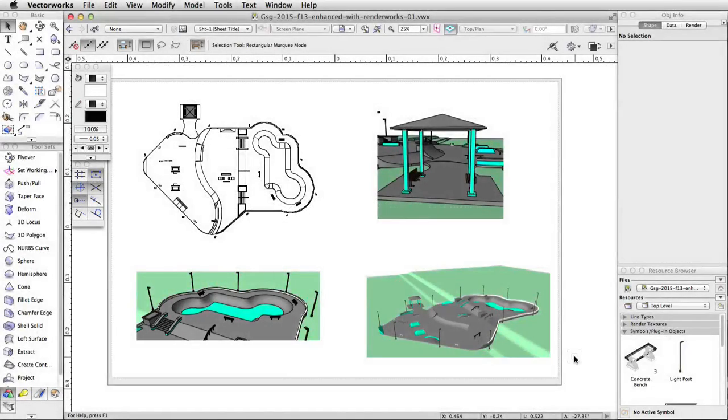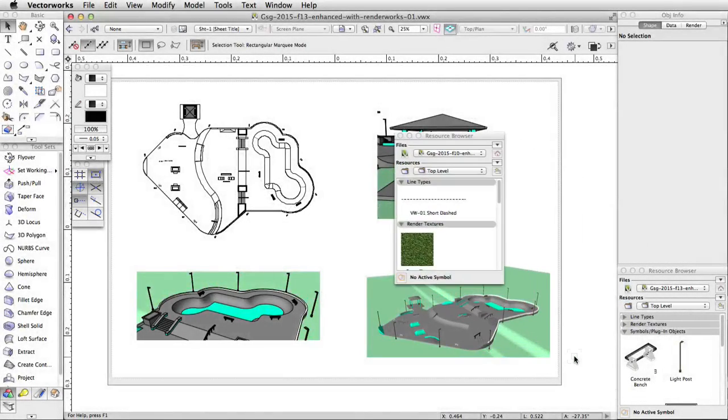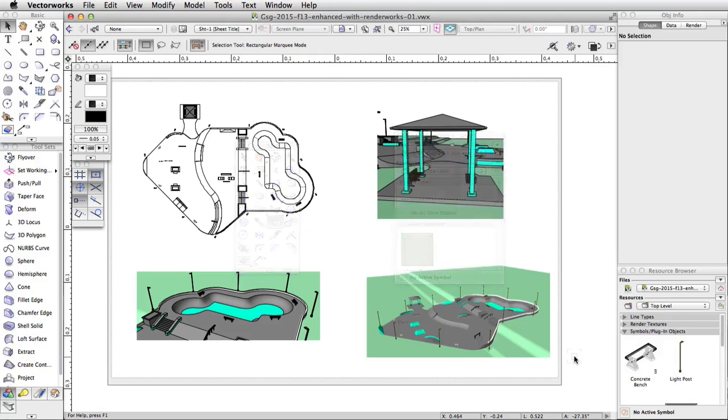In this section, we will import a texture and apply it to the concrete base. We will then use the Attribute Mapping tool to adjust the scale of the texture. Finally, we will duplicate the texture, edit its settings, and apply it to some obstacles in the skatepark.